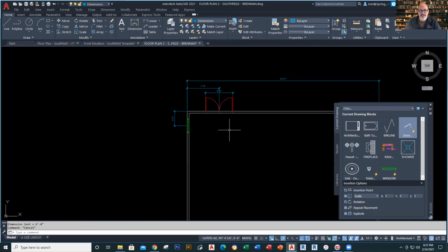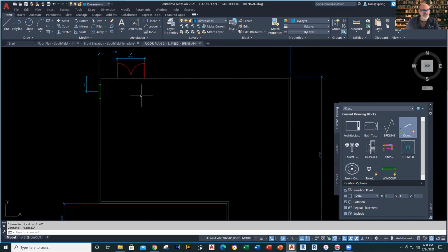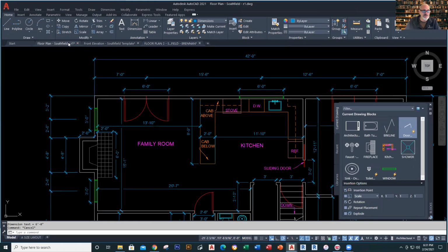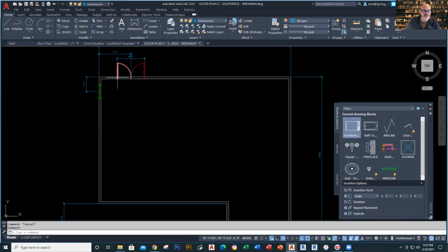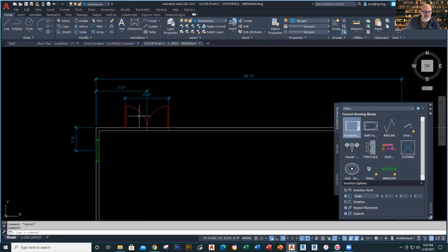So now we've got an idea as far as how to place these doors and windows and so forth. Let's go back to here, make sure it looks right. And you have it right there, so 6 feet, and they actually need to be rotating the other direction, so I have to change that a little bit. The next thing I'm going to do is with these doors, I can take them and click on them. Since they're dynamic, I can click it right here and flip it that way, and this right here and flip it that way by clicking on those doors. Pretty cool stuff.